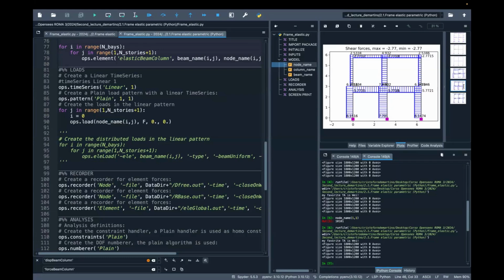Whether it's non-linear or not, if it's dynamic it is a little bit more complex, as Antonio Bernardo was showing before. In that case, you can have the inertial forces playing a part, right? So that's right, Antonio, you should also consider the damping forces playing a part in the equilibrium. But if it's static, whatever is non-linear, P-delta, corotational, this must be satisfied. Otherwise, there is some problem, right? And this must be satisfied also if it's a three-dimensional system, but you have two directions in that case, right? It's a simple equilibrium problem.